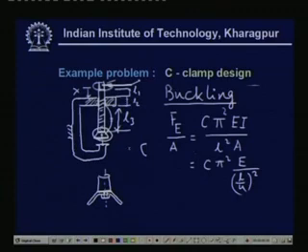Depending upon the boundary conditions, the failure may start at different regions. Here, one reasonable guess of the boundary condition is, let us assume that this part is clamped. That is, here we are considering buckling of a beam which is fixed at one end and free at the other end and subjected to a load P. Then of course, the value of C will be 0.25 in that case, and then we have the Euler critical load for buckling.